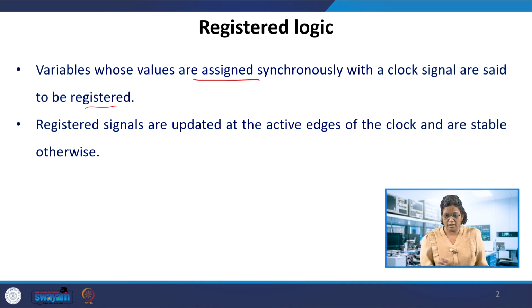If it is registered, if we do the storage with respect to the clock, then it is more stable. It would also avoid glitches in the variable. We can observe that. So registered variables have their operation done with respect to the clock.